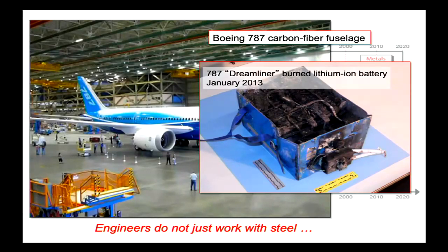It turns out that lithium-ion batteries need a better airflow than the old lead-acid batteries that they replaced. And it was just, let's call it an omission, an oversight by the engineers that they didn't have enough airflow to evacuate the greater amount of heat being produced from the zone. Temperature got too high, the battery caught fire, a problem at the time, no risk to anyone, but the problem was solved, which is one of the great things about being an engineer. You think, okay, problem today, address the problem, solve the problem, no more problems. No one talks about it anymore.